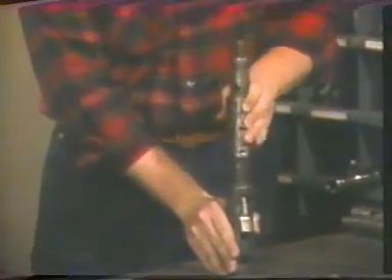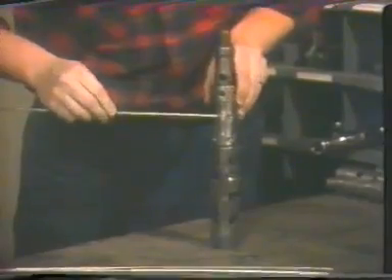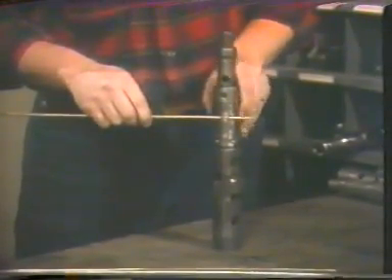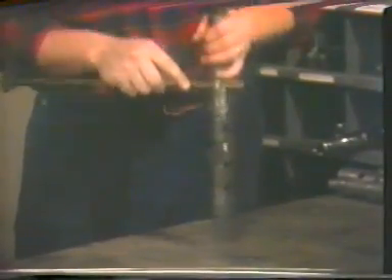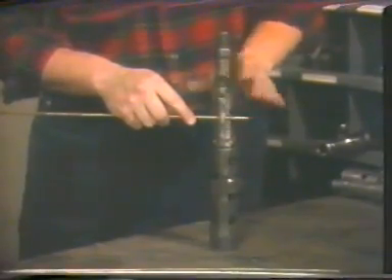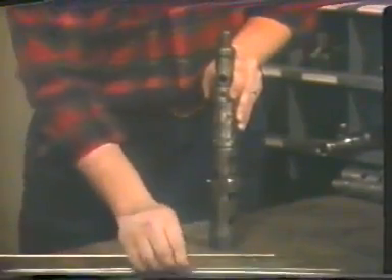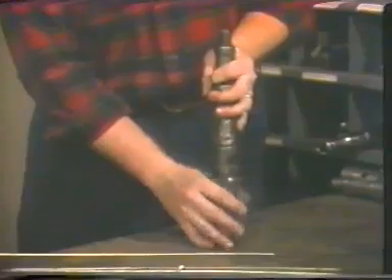In general, these tools are attached to the flow controls by means of shear pins, collets, retaining dogs, or some combination of the three. When the desired depth is reached with the control attached to the running tool, manipulation of the wireline tools places the control in the set or locked position and releases the running tool from the control. This is usually accomplished by shearing a metal pin, which was then used to hold the control to the running